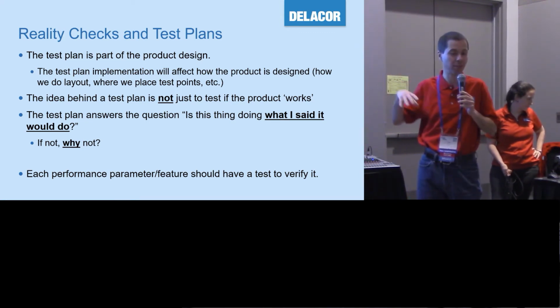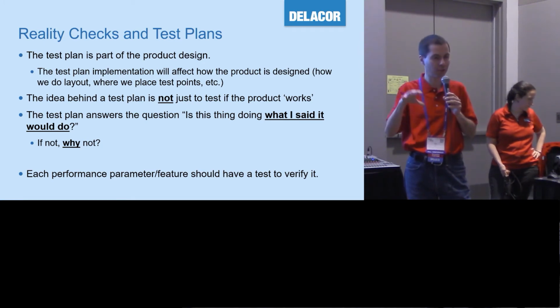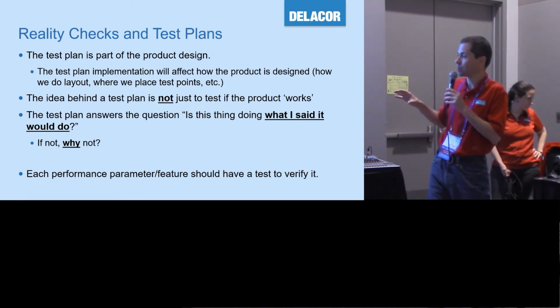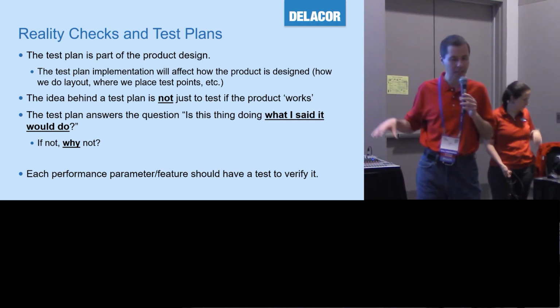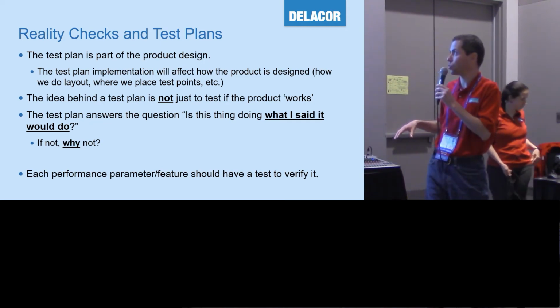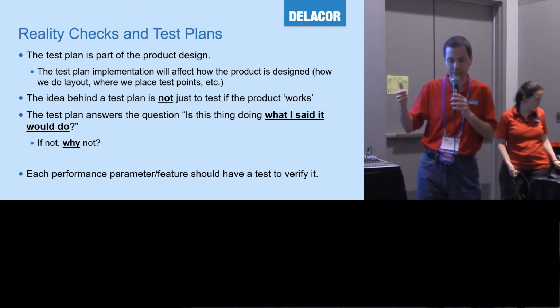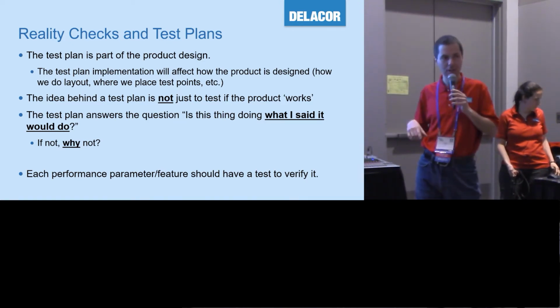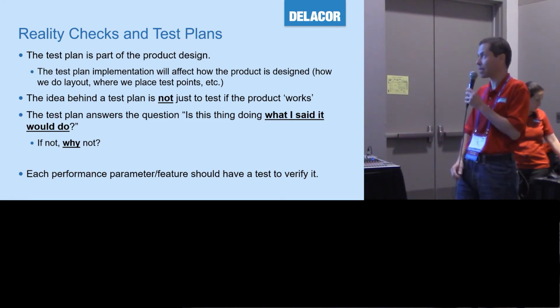Some of these specs may not even be relevant to the customer, but they're relevant to you to guarantee that your product works by design. You need to be able to test them somehow. And if you do that during the design stage, it's a lot easier to place test points and design any built-in little jigs or fixtures into your board than trying to add that stuff later.